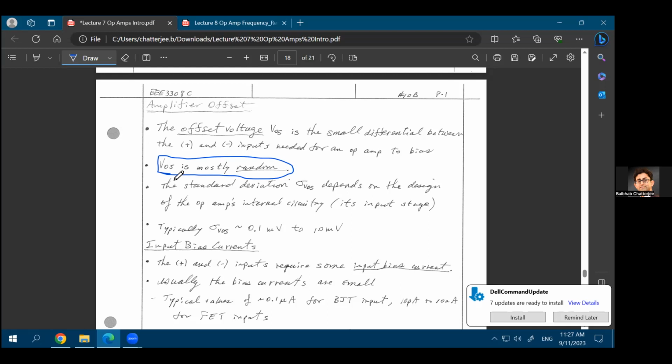Similarly, there will be another MOSFET at the negative terminal. Now, let's say this is the positive terminal MOSFET and this is the negative terminal MOSFET. These MOSFETs are not the same ones. And whenever you are building two different MOSFETs, there will be some manufacturing variation between them. This one will not have the exact widths or lengths or exact connections as the other, even if you intend it to.